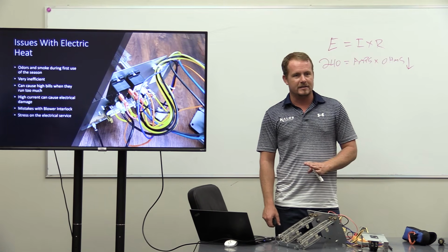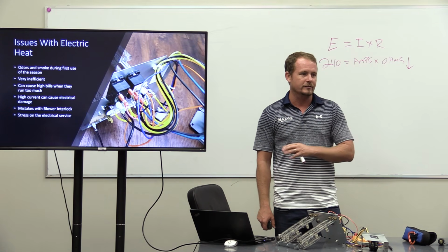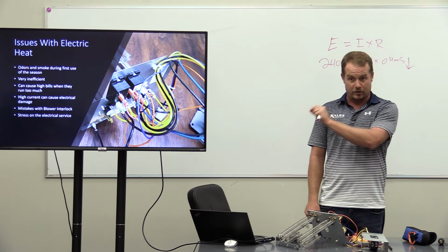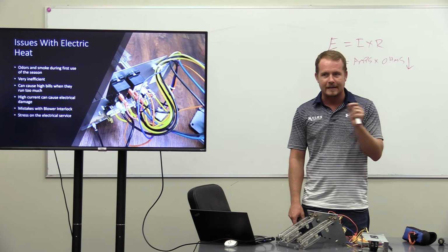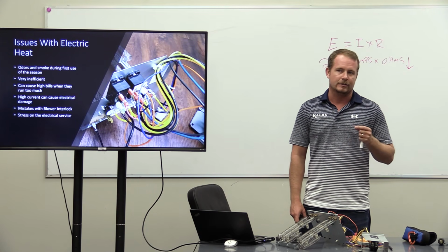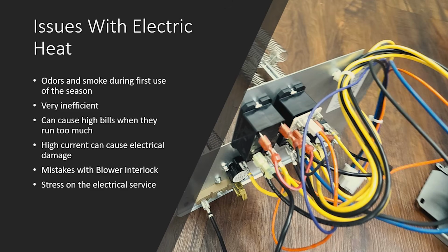With a lot of modern thermostats, you put in emergency heat, it calls for W2. But on older thermostats, and we're going to talk about this, a lot of times that E isn't actually even hooked up. So it depends on how they're wired. Heat strips are extremely inefficient, so we do not want heat strips to run unless we need them to run, and some of the strategies that we use have to do with that.